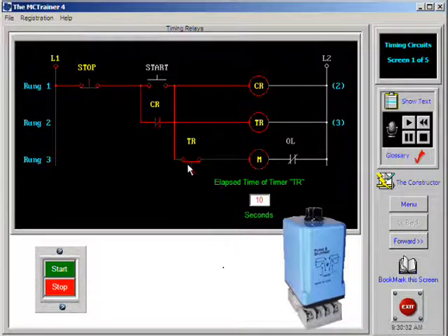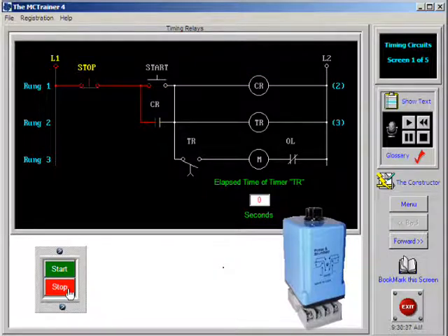The off delay is designed to operate its contacts in response to the closure of an initiating switch. Closing the switch will cause its normally open contacts to close instantly, and its normally closed contacts will open instantly. As long as the initiating switch remains closed, the contacts will remain in their active state. Opening the initiating switch will begin the timing sequence. After the time lag, the contacts will return to their normal state. Off-delay relays will have normally closed, timed closed, and normally open, timed open contacts.